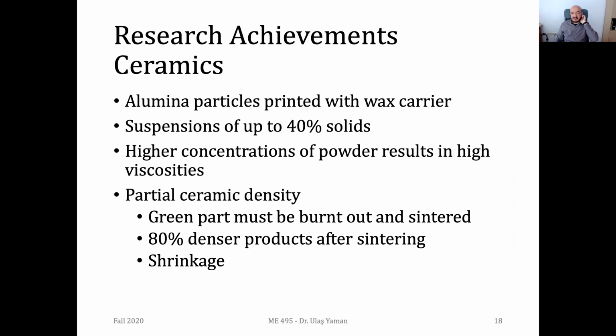And another issue about the ceramics is that if you cannot just jet the material itself, then what you can do is have a kind of wax carrier. So assume that this is the original aluminum particle, which is ceramics, as you know, and then around it you may have a kind of wax carrier. Assume that this wax carrier is blue, and you will have some blue wax around this material. That will actually carry your main material. This red one is the ceramics.